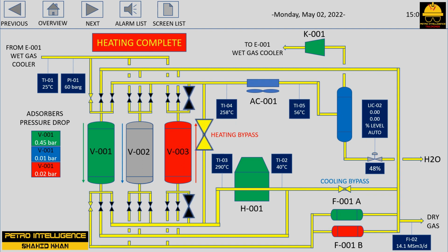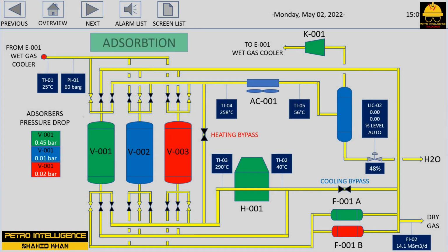There are also connections for treating the bed during the regeneration step. In ion exchange processes, there are generally two types of fixed beds. Single bed systems remove only one type of ions, either cations or anions. Two bed systems remove both cations and anions. The type of bed used depends on the process involved and the desired quality of products.